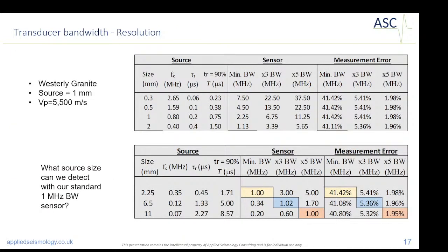And, well, just a quick calculation of what would be the expected error, and the error here is just based on us being able to capture what would be the arrival of our acoustic emission event, and that it's basically linked to what would be the rise time. So we want our sensor to be able to capture in full this arrival, and if there's any distortion to it, then we can calculate what will be the error in estimating that arrival.